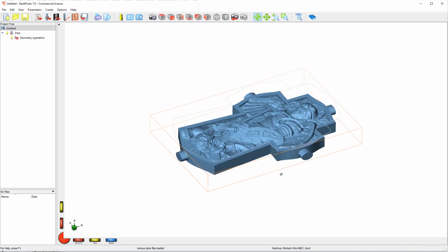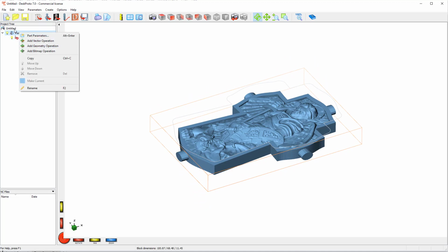This video will be in two parts. I'm going to do just the roughing for now. So I'm going to go up to the part. I'm going to rename that. You can click twice the same as you do in Windows softly. So I'm going to go roughing 317 ball end mill. Now this will actually be written into the code. So if you ever have to open and edit the code manually, it's easier to know what you were doing than try and have a guess what tool you were working with.